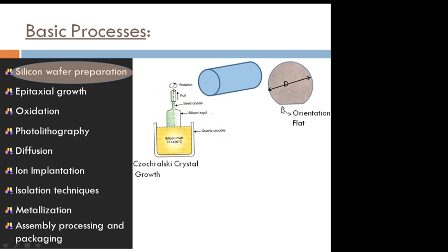Okay, so in short, this flattened part indicates the direction of the silicon crystal growth, the easy axis. Further, after the flat of this slice, there will be many logical separations of this area of the entire cylinder, meaning perfect squares, except at the edges where it is not a perfect square, which are going to be waste. Otherwise, the pure square ICs or chips are used for further development of the fabrications.